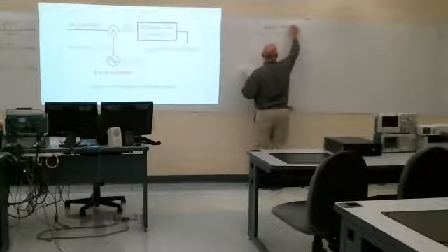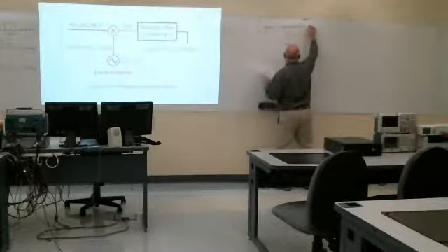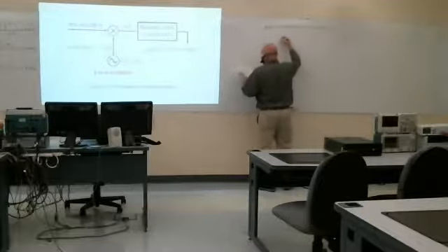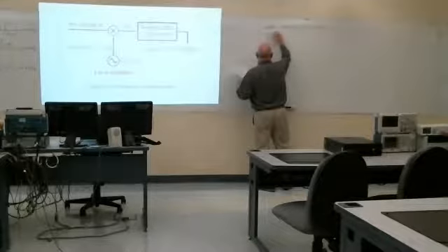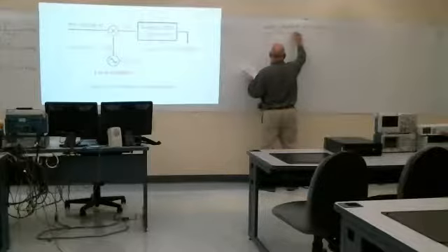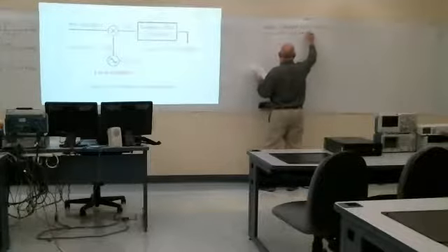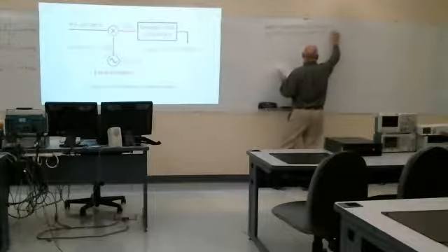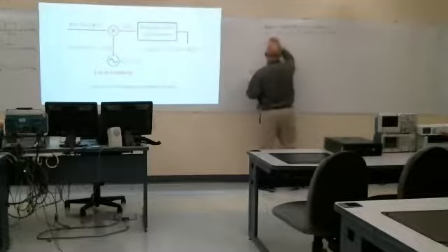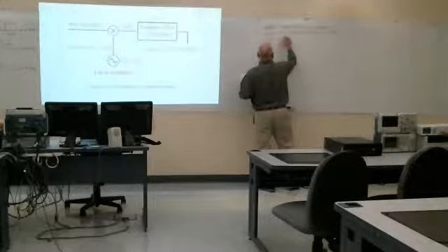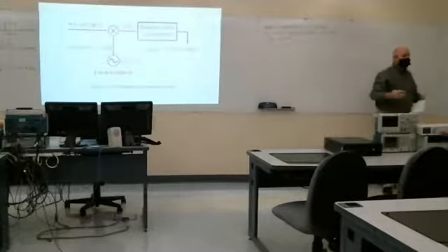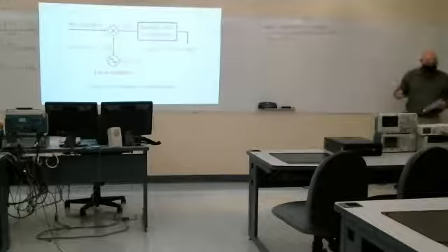Modern receivers use a tunable oscillator and a mixer and fixed bandpass filter to select the station. So the idea here is we can build a really high quality bandpass filter. It only has to operate at one frequency.